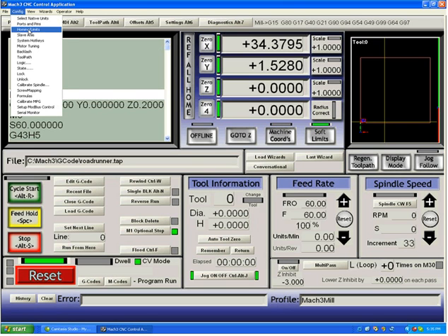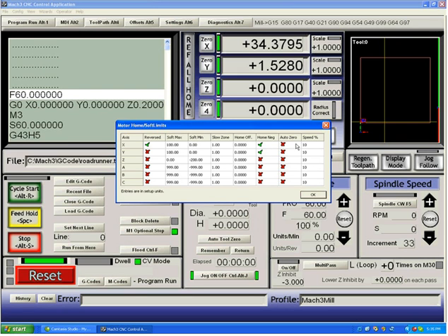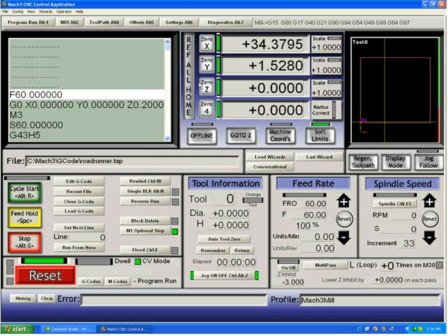And if we look at Configure, Homing and Limits, you'll see there is an auto zero checkpoint. These, for most users, should be checked for all axes that you're using. This will zero the coordinates of the machine coordinates and stop you from getting confused about how to zero. So we say OK to that, and let's re-zero our system.